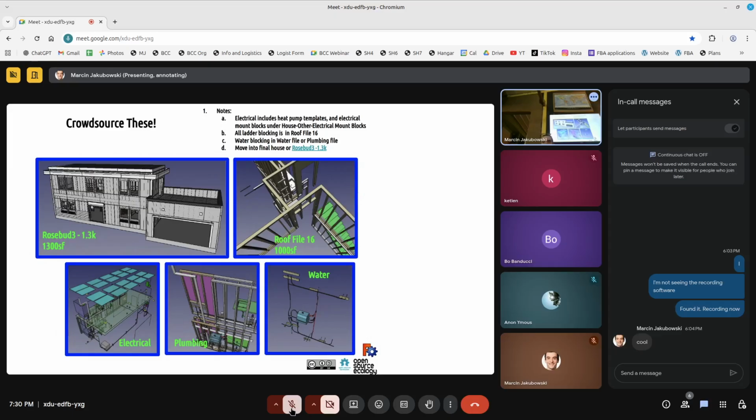Electrical, everything out. The utility channel is not a big deal. What the inspector will look for is that you don't have any wires less than 1.5 inches from the surface, which this does, because you're just running the wires under a panel. But if you get a good inspector, they won't say anything. If you get a really picky one, they will, because they say, oh, well, what if somebody nails into it? Well, there's no nails in that area. But they might not go for that. So it's kind of one of those little gray areas. But utility channels are a common concept.